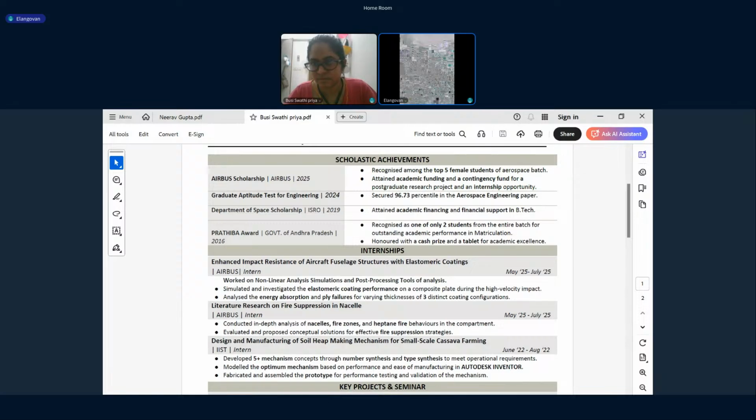This lift twists the wing, giving additional angle of attack, which gives additional lift, which again gives additional angle of attack.